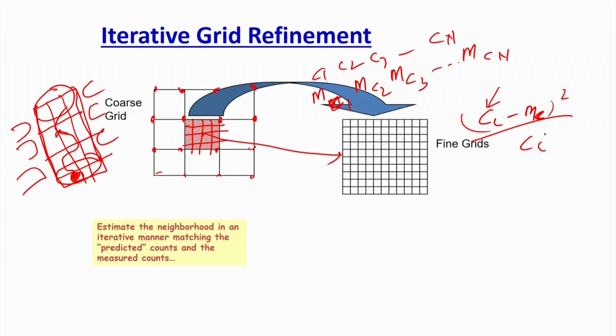I first divide it into a coarse grid, and then we divide it into smaller parts. Then again I will do the chi-square test everywhere, and find the location where the chi-square values are lower. So this position. Again I will do the same operation, and keep on reducing it further, discretizing it again, until I achieve my minimum resolution. The grid size should not be lower than the resolution of the particle location, because that much is the particle uncertainty.